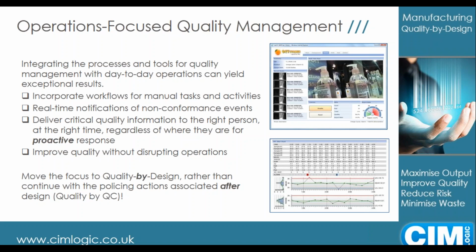Using an electronic or systems approach rather than a paper-based approach, we should be able to improve both the accuracy and the timeliness of the data that we collect. So rather than doing end-of-batch single sample tests, we have the opportunity with modern technology, modern equipment, to do complete inline checks. We could check the weight of every bottle as it goes past a check weigher and record that. We could check samples on the line if we need to take samples at a particular time, and do that in real time and ensure that it's done in real time.